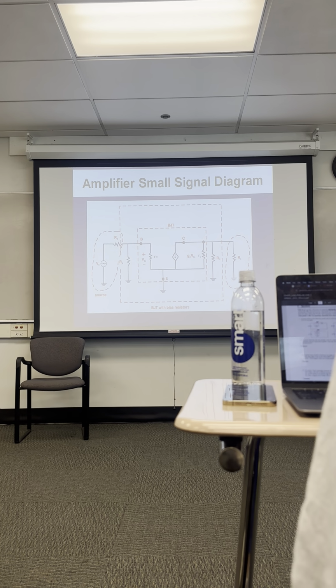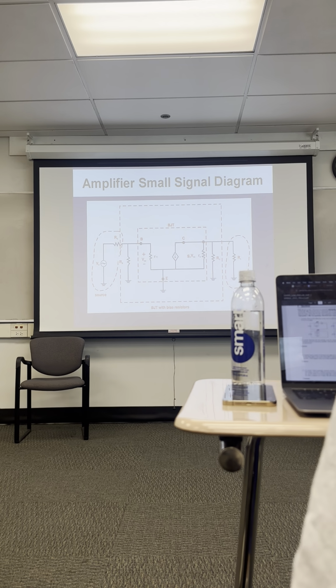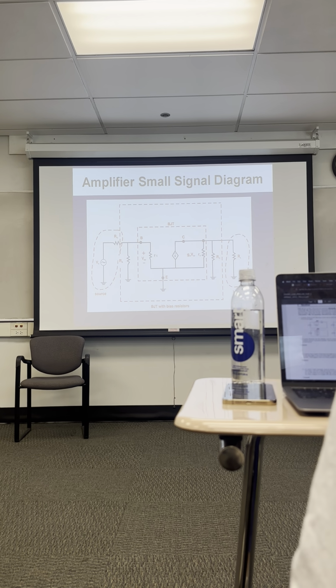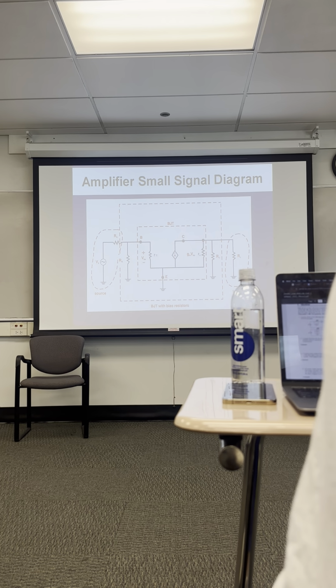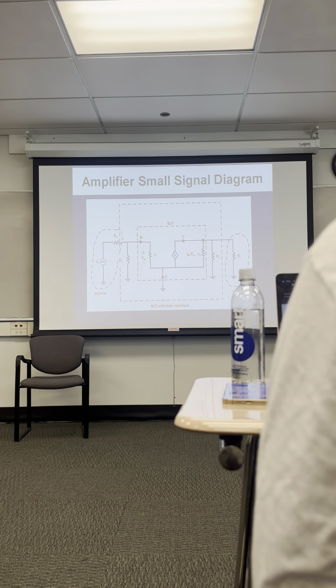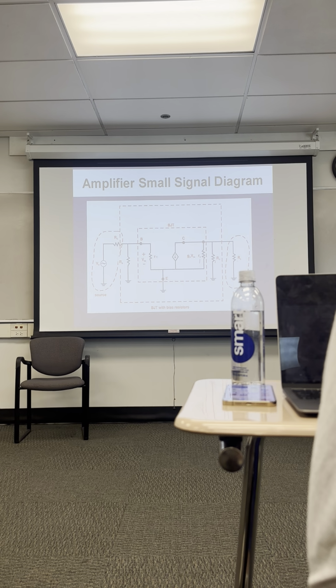So this is, from memory now, our small signal diagram of the circuit. You notice the emitter is grounded, and that's because of the capacitor across the emitter resistor. R_B, the two resistors in parallel, appears here. Here's our r pi. Over here, this is r_o. Here's the collector resistor, R_C. And here's the load resistor, R_L. And then on the input, this is our source resistor. So r_o, R_C is in parallel with R_L.